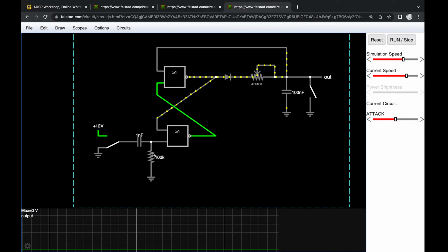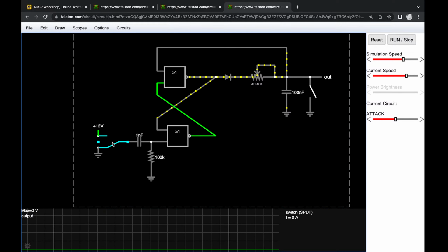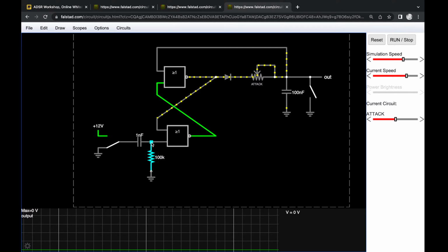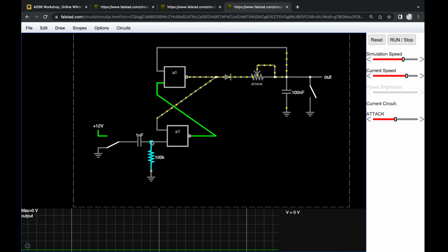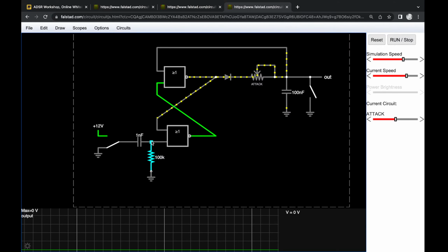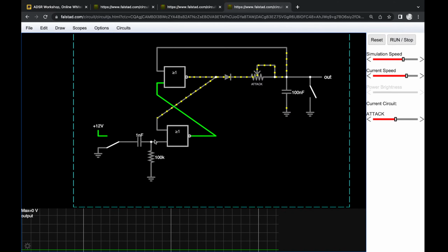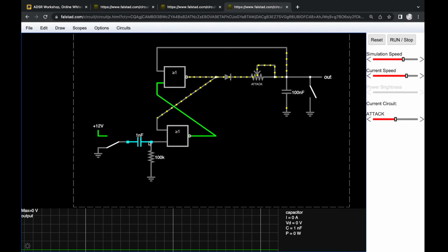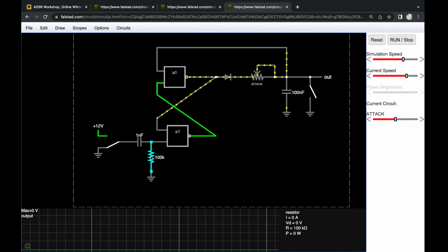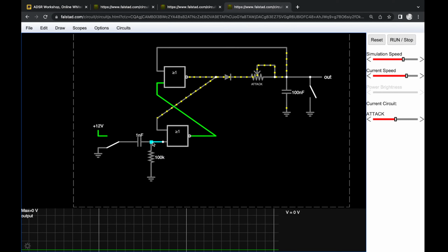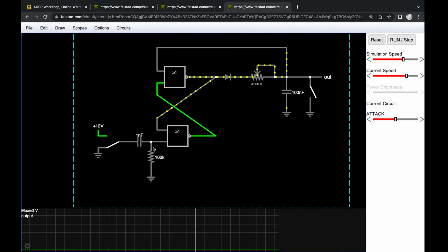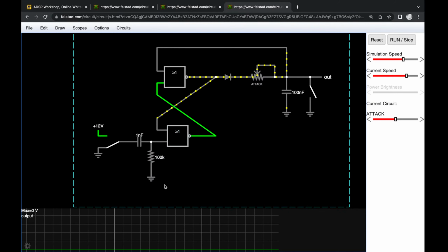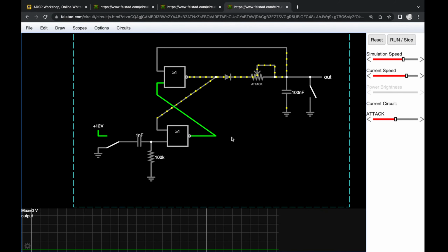I've put this high-pass filter there because now whenever I flip this on, we just get a short voltage spike at this point and it instantly goes down to 0 volts again. That way we can make sure that set and reset are not, or hopefully are not going to be 1 at the same time, right? Because this is only going to be a very short spike. And here, it takes a while until this goes high, so we should be in the clear with this. That's why I've put the high-pass filter here.